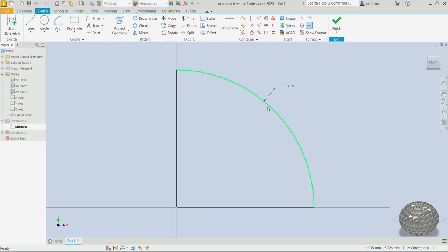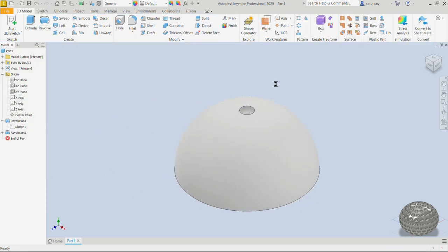The next one again at an angle of 45. We'll do 60, 75, and then finally 90 here. We'll then circular pattern them individually so we can get all the dimples we have on half of the golf ball. Let me finish this and continue. We'll get a clearer picture of that as we go on.